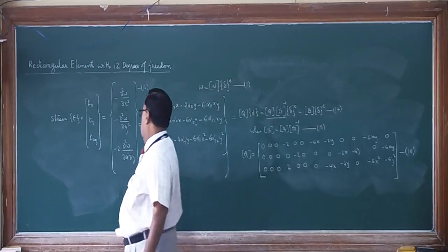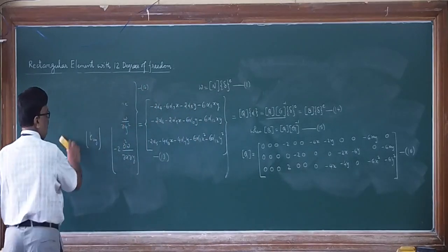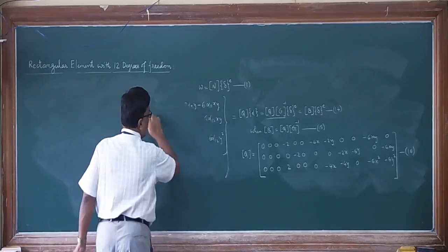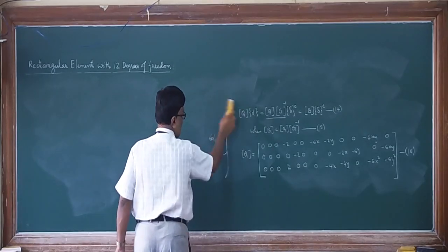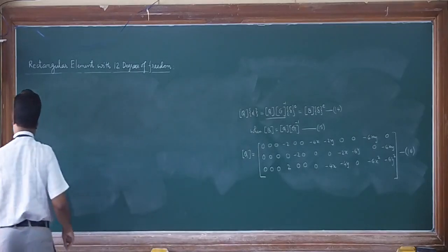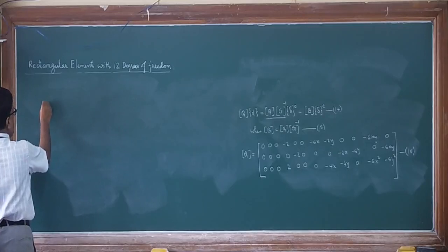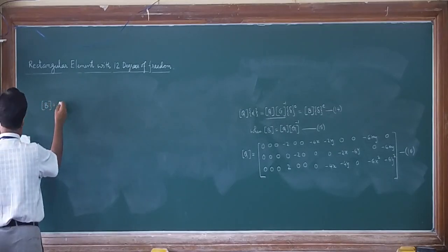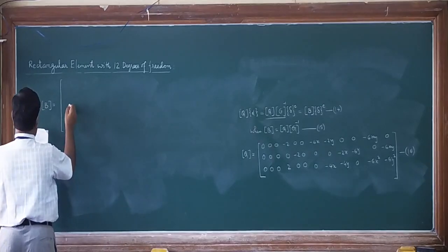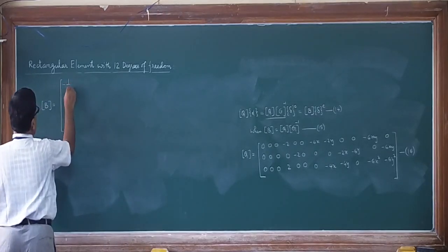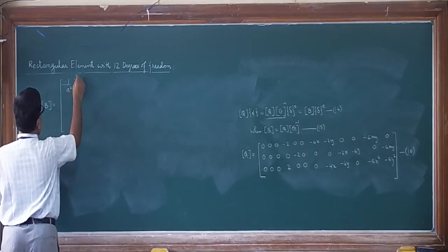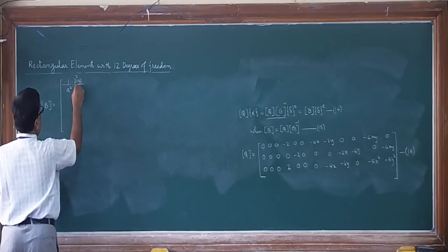So this is the Q, and after multiplying this Q with the G inverse, what you get is the B matrix. So let me quickly write how exactly we can write the strain displacement matrix for this. So therefore, from equation 10, B can be written as minus 1 upon A square, dou square Ni upon dou zeta square,